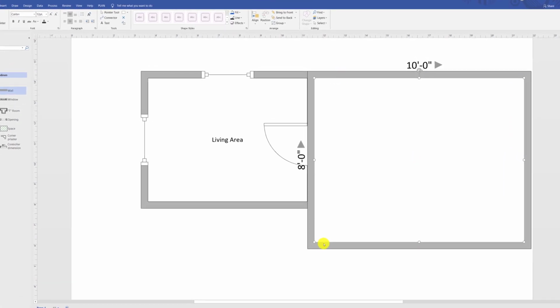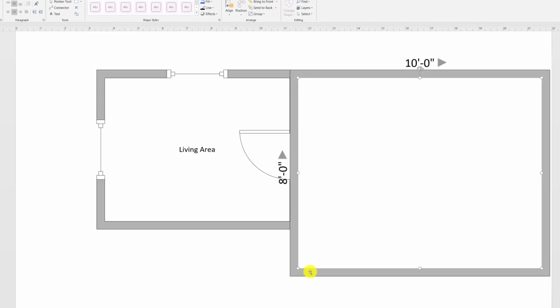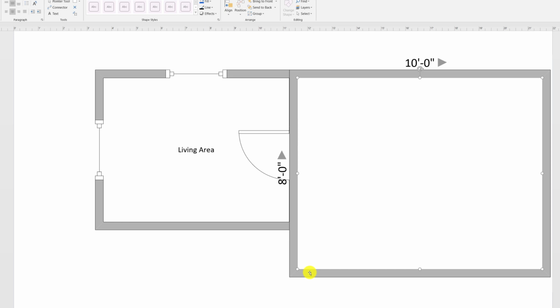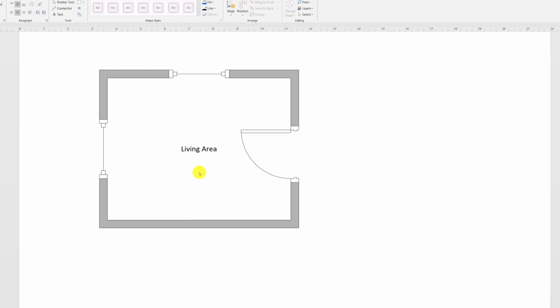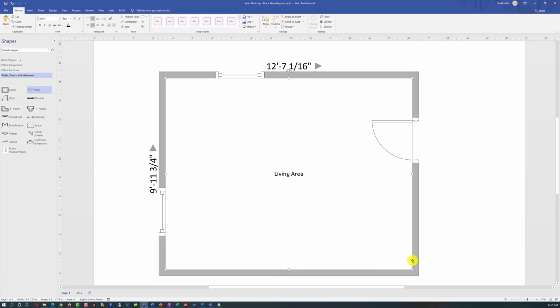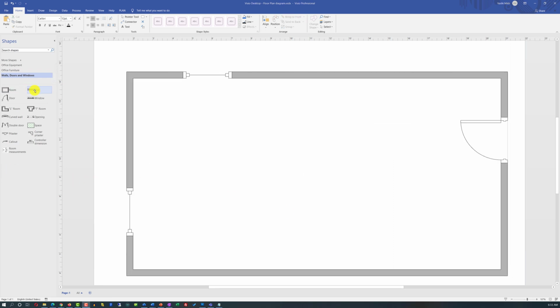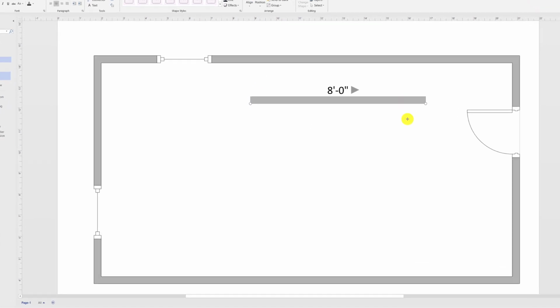You might also consider expanding your floor plan differently. To do that, we will delete the room that we just dragged into the diagram, and I'm going to do it by clicking the delete button on the keyboard. Instead of building space room by room, we will use this room shape from Microsoft Visio to define external dimensions of our structure. You can start defining the walls by using the wall shape. To do that, you just need to drag the wall shape and snap it into position.